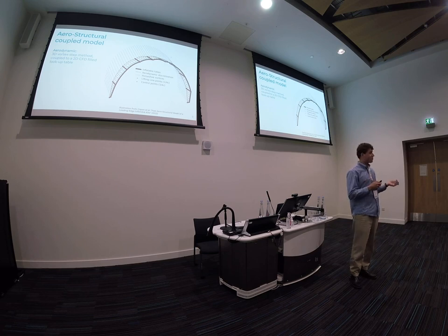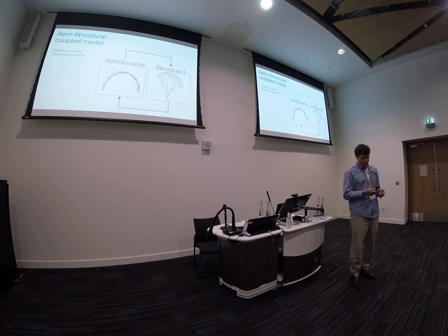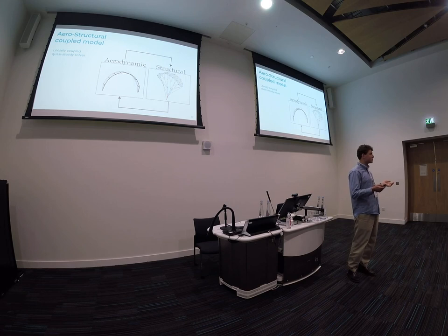So both aero and structural model are coupled, loosely coupled in fact, and formulated in a quasi-steady way, which means that whatever temporal time step, we assume there is a convergence. Okay, so we have a kite model. It's great. We know we need to deal with actuation-induced and aerostructural coupled deformation. And what can we do with this model? How can we help the kite design process?